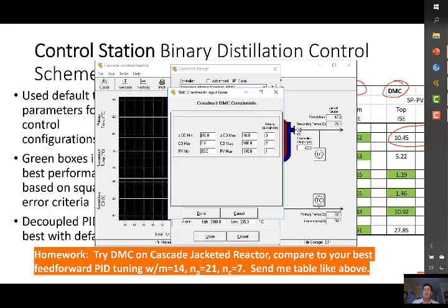So in this, this tells me you don't want the temperature deviating very much or very fast, and it has a very narrow range here. Moving the valve is the next most important thing. It can go fully closed or fully open. Most operators in industry don't like fully closed and fully open. Things get stuck. They would rather see 2 to 5% here and 95 to 98% here. And then the change that you're allowed to make in the valve is limited in this controller, but that's given the lowest priority. And here, 1 is highest, so 3 would be the lowest.